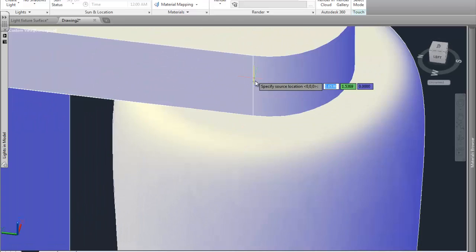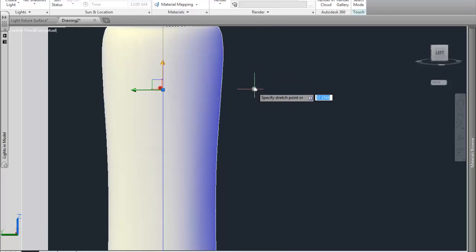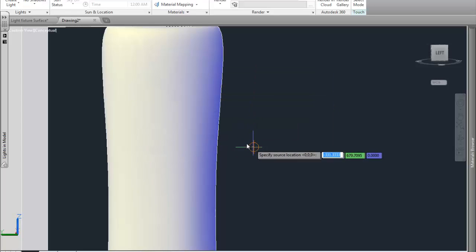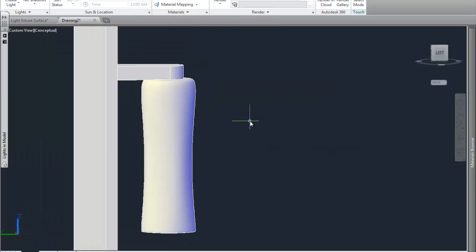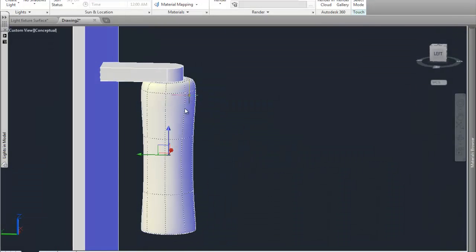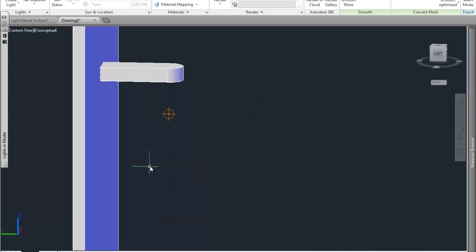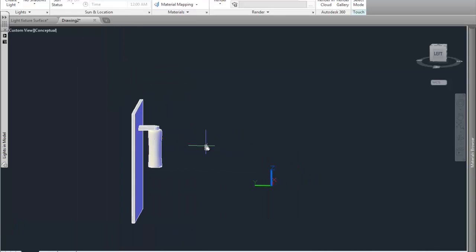Let's see if I can do, oh there you go, it snaps into the center, accept it by clicking enter, and I move it down to about this position here. I hope it's there. Yeah, it looks like it's there. You can check by taking the object, right clicking on it, going to hide object, you'll see the light. And to get that back, just go end objects isolation, and have it back.